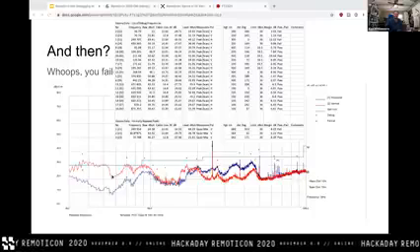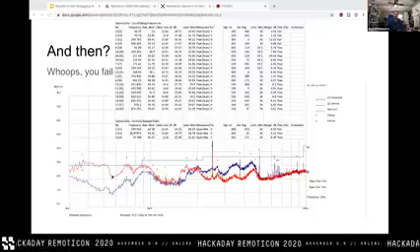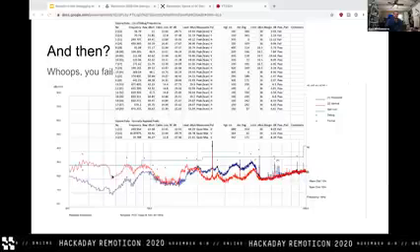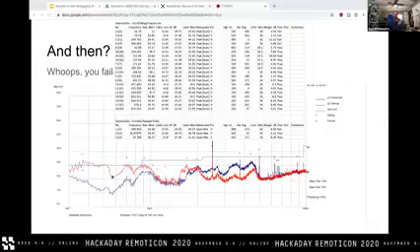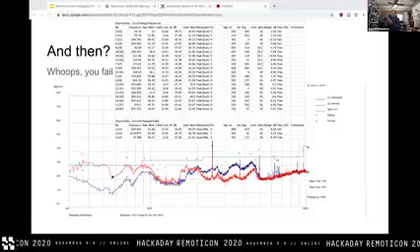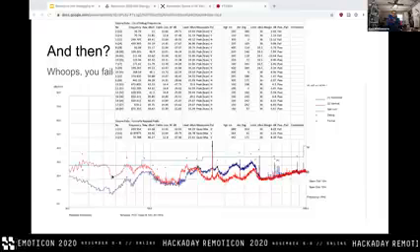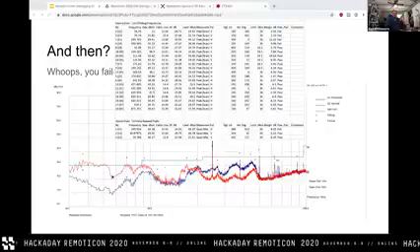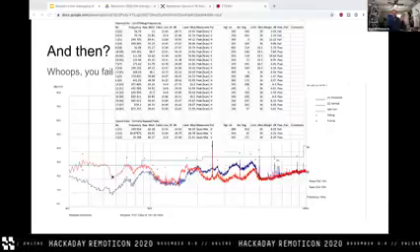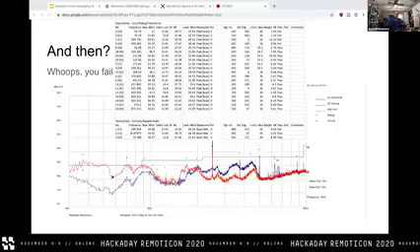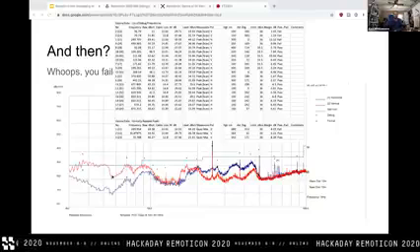For time immemorial, the only practical way to do this is basically make a device that measures the received power at a specific frequency, and then just tune that specific frequency through time, ideally as quickly as you can. Listening to this frequency, then move to the next frequency and listen, then move to the next frequency and listen, and so on. That's swept spectrum analysis.